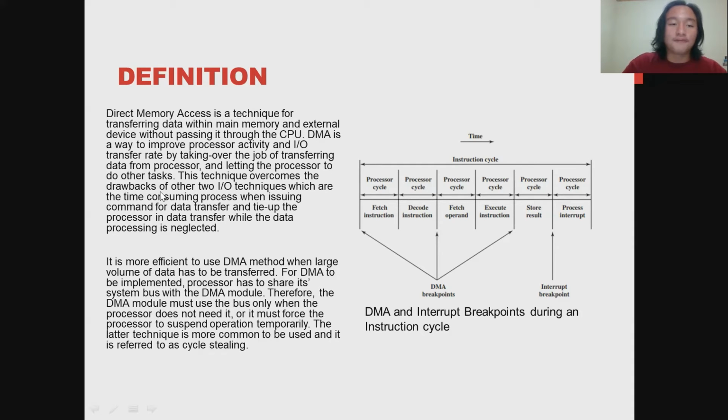This technique overcomes the drawbacks of the two input-output techniques, which are time-consuming when issuing commands for data transfer, and tie up the processor in the data transfer while data processing is neglected. It is more efficient to use the DMA method when a large volume of data has to be transferred. For DMA to be implemented, the processor has to share its system bus